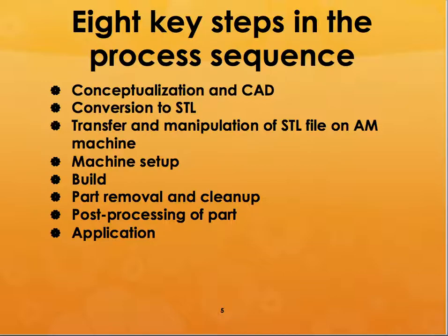Then you have to remove it, and suppose it is built with powders, there is going to be powders sticking around all over the place. Or if it is some kind of a solution or a solvent or some kind of a resin, there is going to be resin. So you have to typically remove that, and sometimes these components are for show and tell, so you have to make it look really pretty. Which means you have to remove that and clean up and maybe paint it or maybe coat it with a metallic coating and things like that. So that will give you the post processing of the part, and then finally the application.